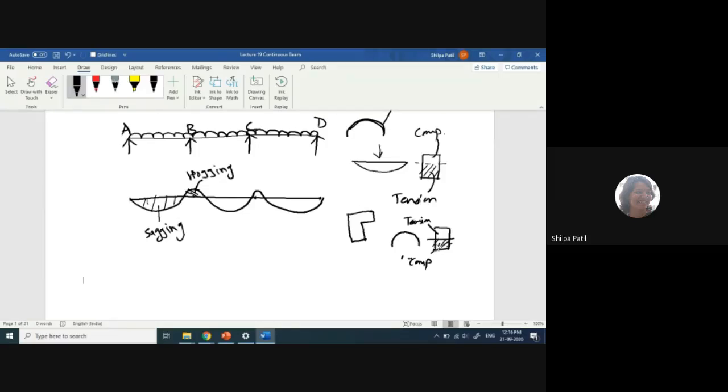So in this case, the slab, where it is lying now, it is in the top part. The slab is in tension. Okay, the concrete present in the slab is in tension and we have to ignore it. So the slab part is ignored above the support in case of a continuous beam. And hence, if I want to draw the cross section for the different spans in a continuous beam, for the mid span of the continuous beam, I have to design the beam like an L beam, okay, in which I have to consider the resistance shown by the slab also.